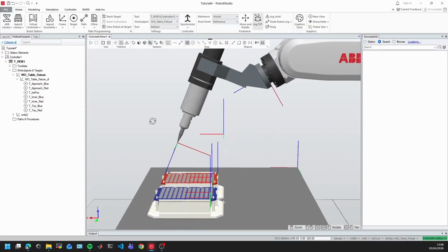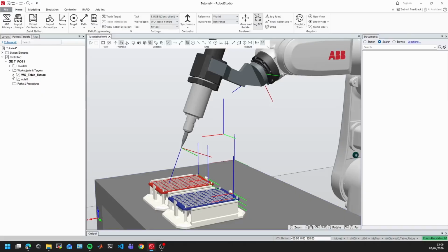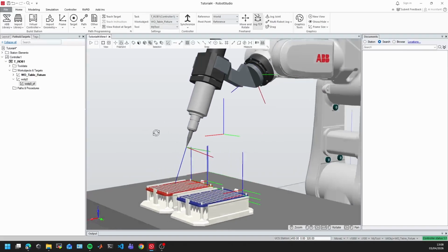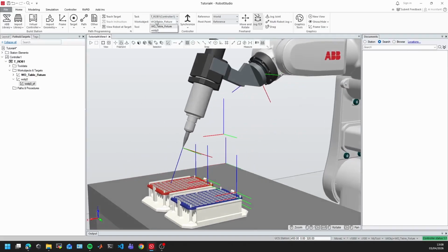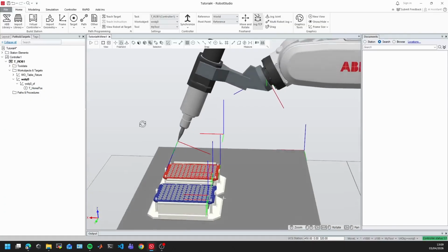Okay, now I have my init position and the other 3 positions. In work object 0, I haven't created anything yet, but I'm going to create the home position there because I want to leave it as the home position. So I'm just going to change the work object to work object 0, and do a teach target. Yes, I know that is in work object 0. Now I have a target there, which I'm going to rename target home pose. There you go, that's the home position.